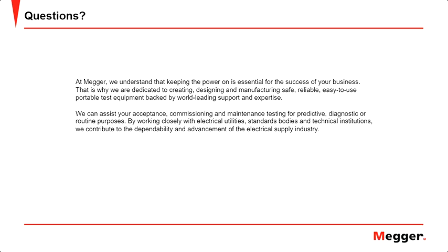All right. Throwing things over to Chase. What is Megger's point of view on partial discharge monitoring of medium and high voltage cables? Does Megger have any products that can monitor PD? Megger's viewpoint on partial discharge monitoring of medium and high voltage cable is that it's absolutely wonderful for localizing where your fault is, depending on whether it was maintenance or acceptance.